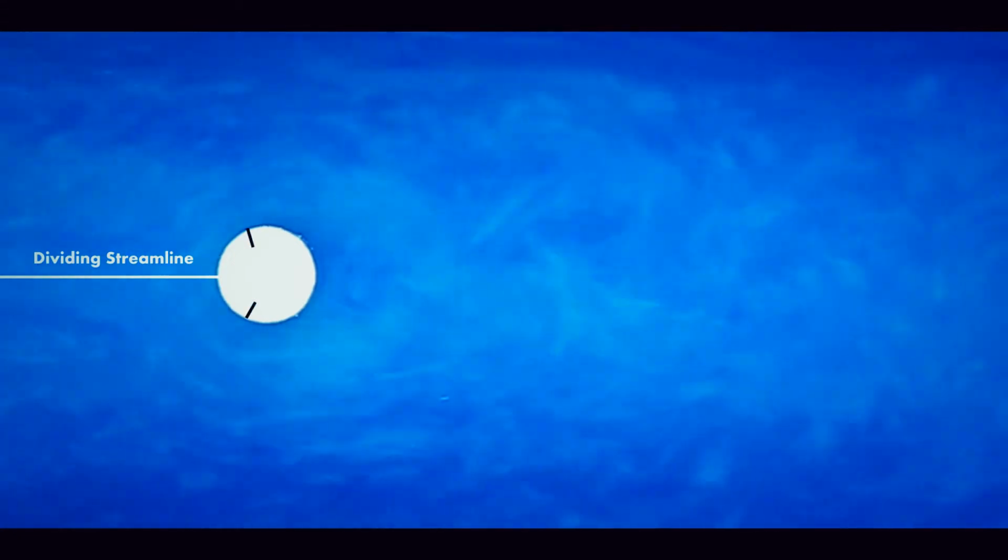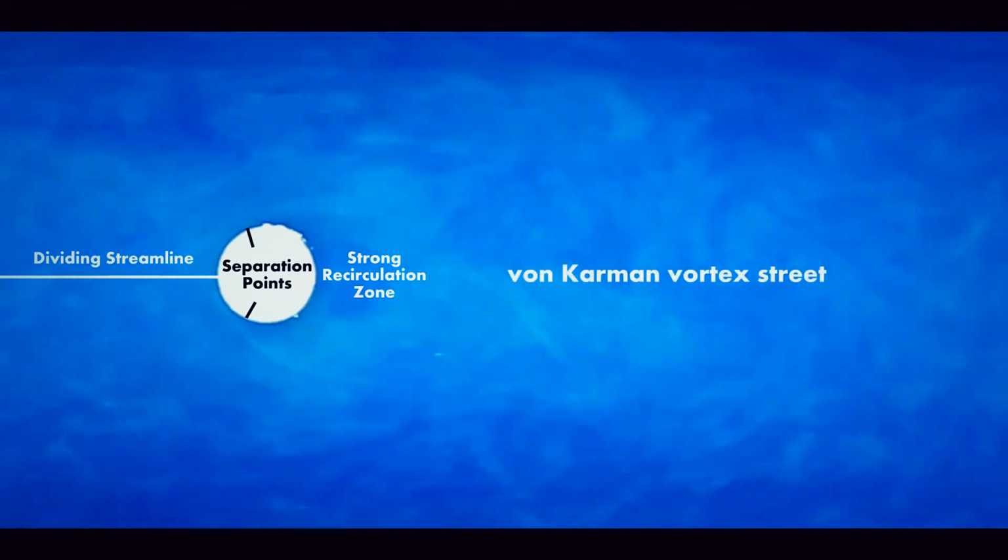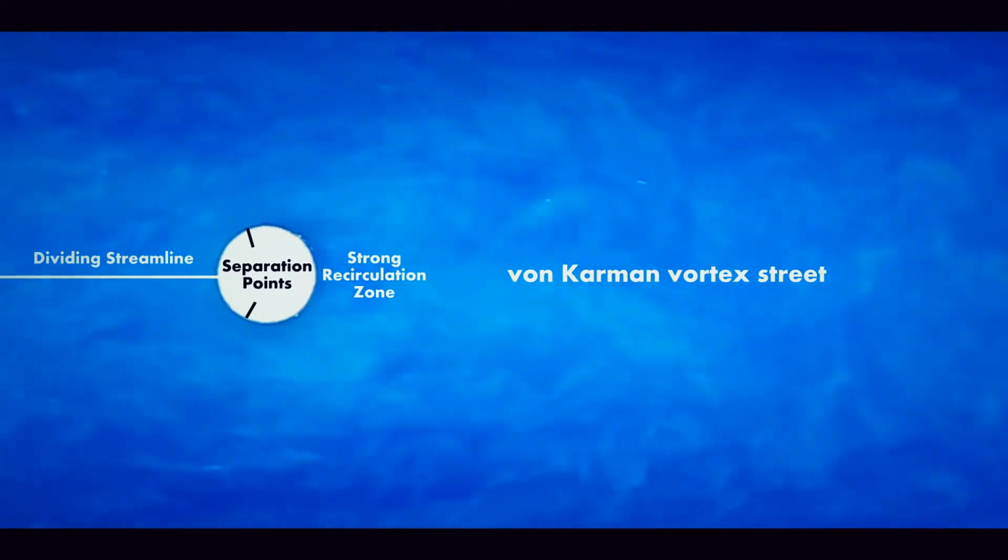And so here we can see flow over a cylinder, and we have a dividing streamline on the upstream side, and then I'm going to note a couple of points on the front of the cylinder. Those are separation points. So you'll notice the flow is separating at those locations. That's where the boundary layer is separating from the cylinder. Downstream we get a strong recirculation zone. That would have negative pressure, low pressure, and that's what leads to the form drag.